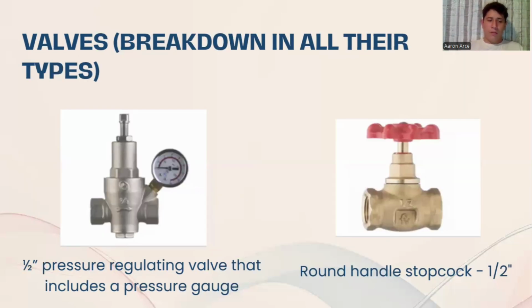The half-inch valve has a smaller diameter, which limits its ability to handle a larger flow of water. It is suitable for applications where the water flow is not very high, such as in homes with a standard residence water system. The 3/4 inch valve has a larger diameter and can handle larger flows of water.